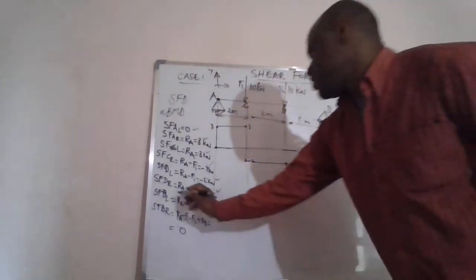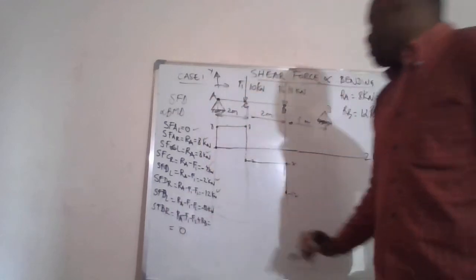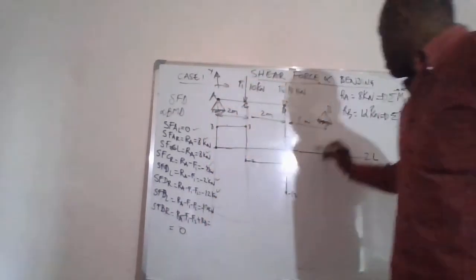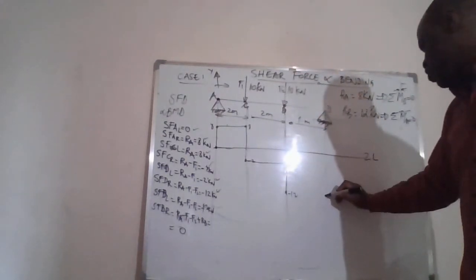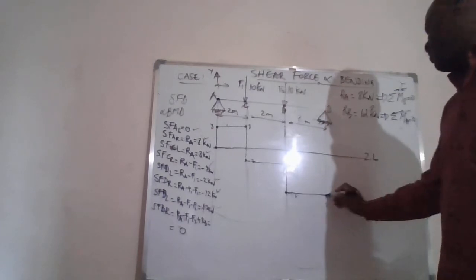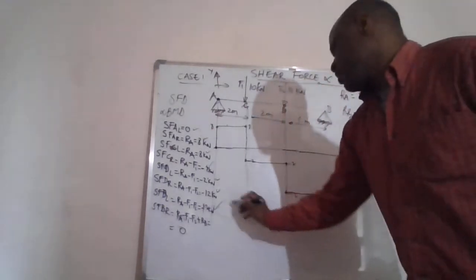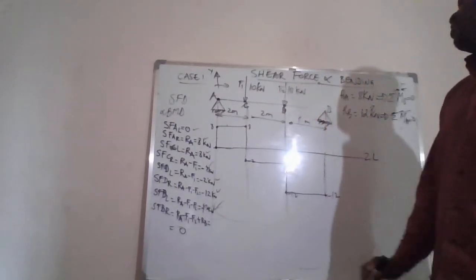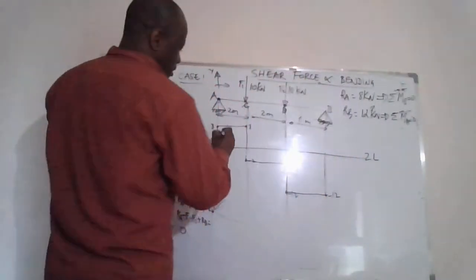Then we're going to B. B left, minus 12 as well. This is B, minus 12. We'll join it with the previous point. And we're done. And then 0. We got back to the 0 line. And this is our shear force.